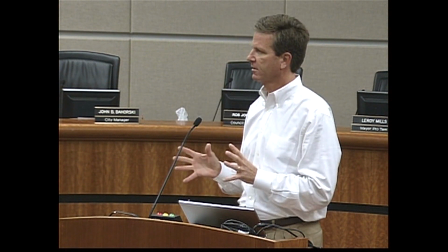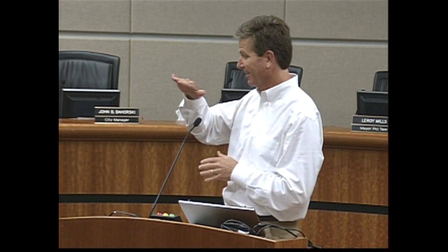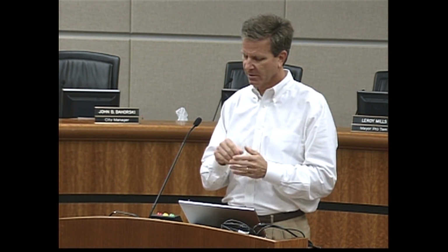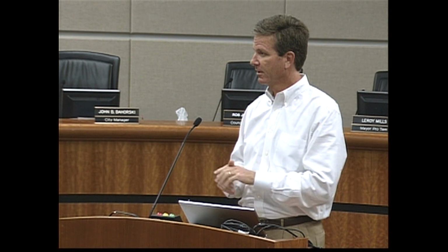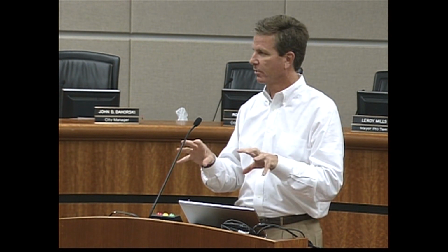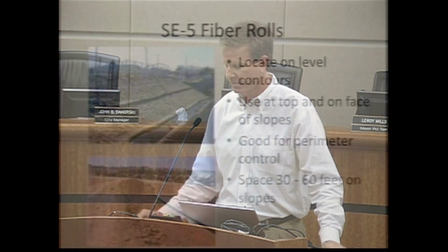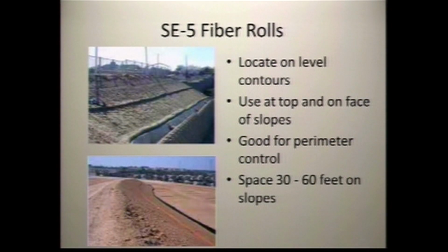But these need to be installed very carefully, kind of along the lines of a silt fence. If you can see light underneath it, the water's going to blow right underneath it, and it's not going to do any good. They need to be trenched in and staked in really well to make sure you have that contact with the soil, so that the water does have to stop when it hits the wattle, as opposed to, again, just blowing underneath it. And you can kind of see in this picture, these were well installed. There's a little bit of sediment built up behind the wattles. They're working exactly as they should be.